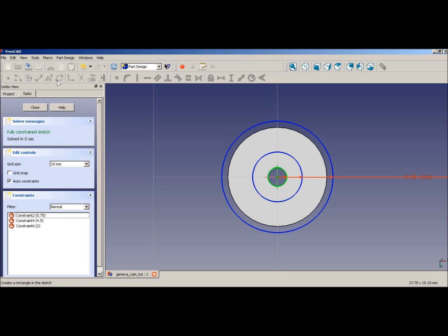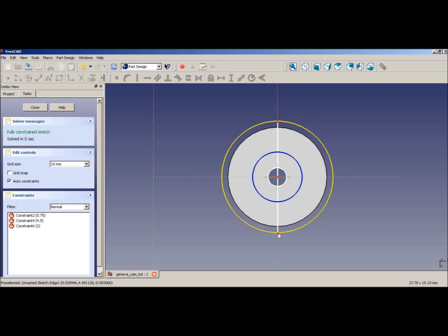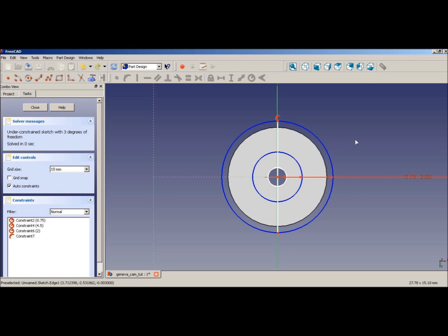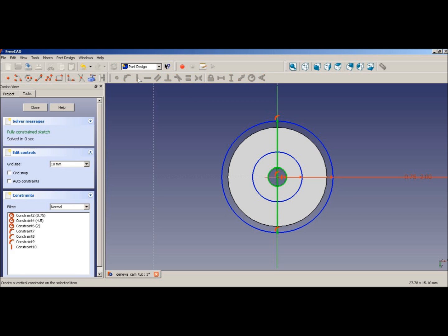and we will start adding some more construction lines in. If the auto constraints are on, it'll auto tangent it, so we'll shut those off, and we'll set all the constraints up by hand. So we'll set a constraint to the inside, or the origin, and we'll set a constraint to the outside of each one of these circles. Alright, and then we'll keep creating lines every 30 degrees.